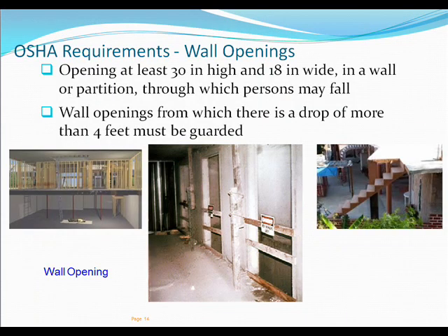Wall openings. An opening at least 30 inches high and 18 inches wide in a wall or partition through which persons may fall. Wall openings from which there is a drop of more than 4 feet must be guarded.